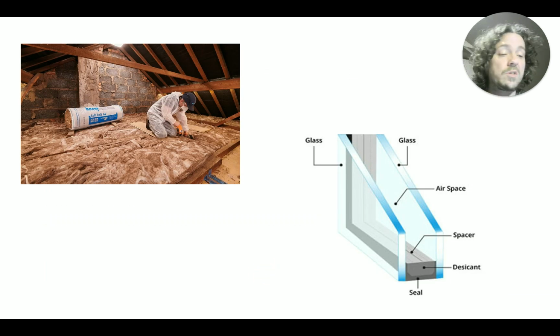So here are some images. Loft insulation. So people will install very, very thick loft insulation, which is this, like, you might have seen this fiberglassy, kind of wiry, nasty stuff. You'll notice the person working with the loft insulation is wearing a mask, which is absolutely necessary because any of these little fibers can get into your lungs and cause all kinds of damage. Don't mess with that stuff, okay? Not good stuff, but excellent once it's in the attic, of course, preventing the heat energy from escaping.